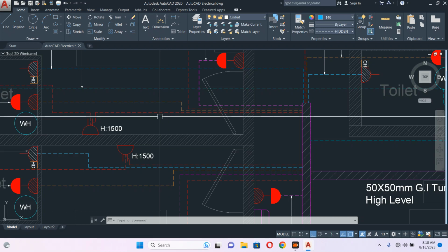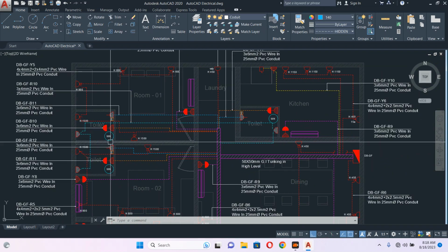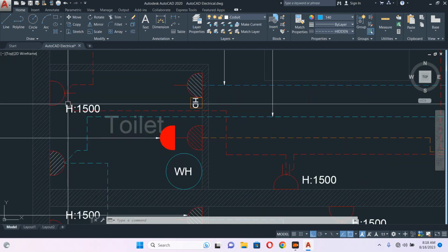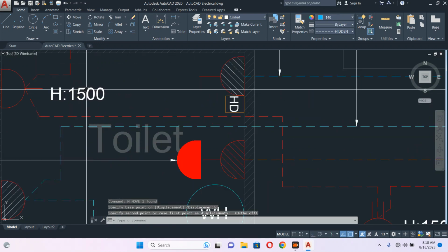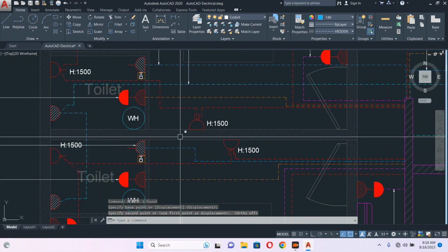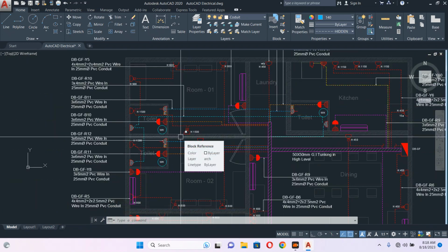This is the tendering stage. Then once we got the tender, they will provide another drawing, from tender to IFC, issued for construction. So you can start construction based on that drawing. Then from that drawing we have to make shop drawing. This shop drawing will be provided to site to do the work. Then we have to make as-built. So there are 3-4 steps: tendering, then the IFC, then the shop drawing, and finally as-built. So actually 4 steps.